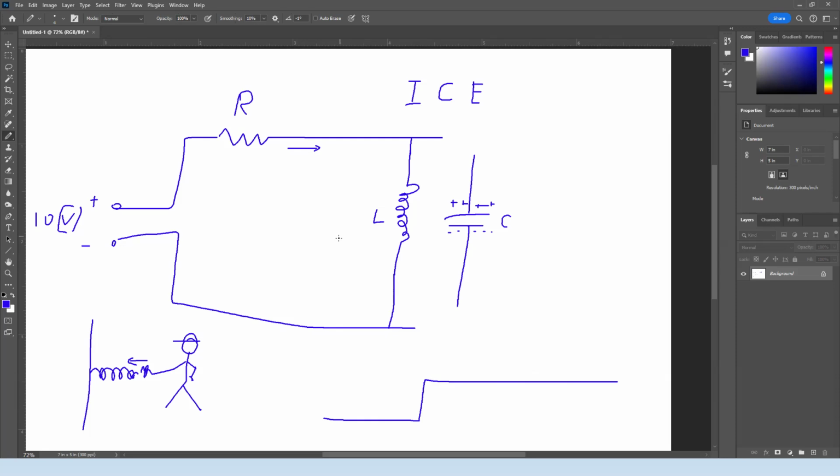Sorry, I just touched my microphone. So what happens in this case, we get a complete opposite of what's happening in the capacitor, which means within the coil, because it opposes right away, it's going to act as a huge resistor. So here's the coil side of it, which means if it acts as a resistor, it's just like as if this was broken.